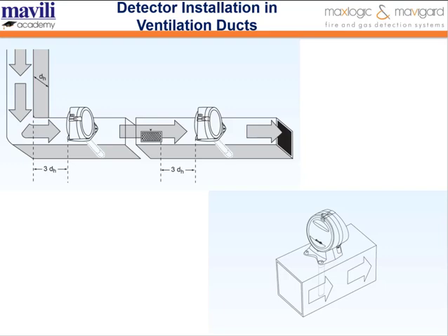For example, imagine a room where a ventilation system is extracting contaminated air to maintain air circulation. If a fire starts near the air extraction point, the smoke may be pulled directly into the ventilation duct. In this case, the smoke might not reach the standard room detector immediately, because it is being drawn into the duct system. During this delay, the fire could continue to grow.